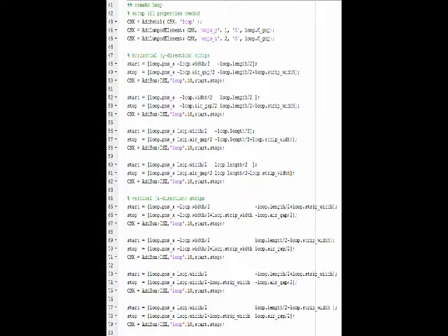As I mentioned, line 64 to line 79 basically repeat the same process as in the Y direction. Therefore, we also have the starting point and stopping point, and they will be the parameters taken by the addBox function and saved back into the CSX structure. Repeating this process 4 times, we finally finish the Z direction strips. Therefore, this whole big piece of the loop antenna is finally finished.